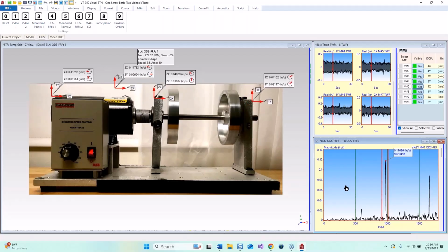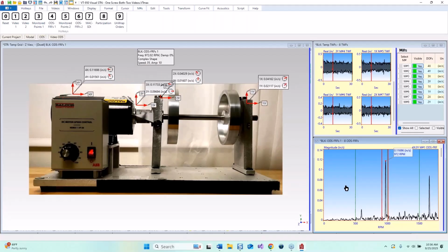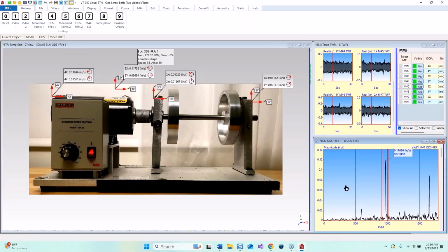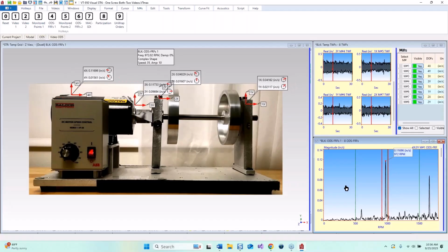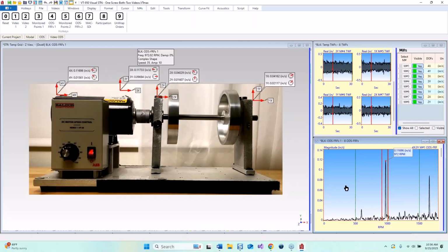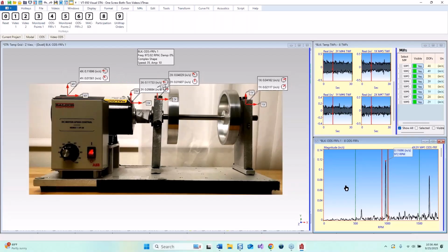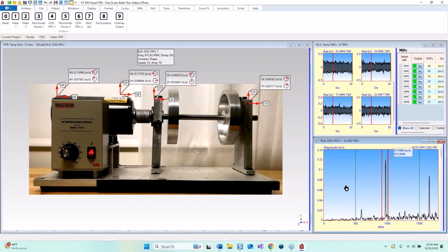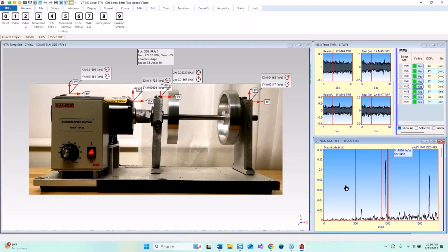We don't have any anti-alias filters in a video. So this is another, you might call it a limitation of the video, but in fact, the video has captured all the vibration between 1800 RPM and 3600 RPM, only it displays it in a different place.